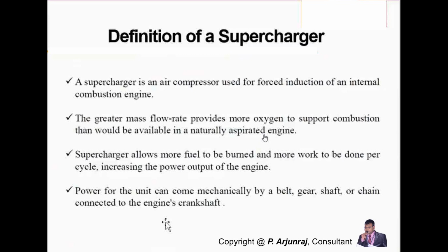And here this supercharger will help for increasing the mass flow rate of air, by providing more oxygen, and more oxygen will help for better combustion. That would not be available in the case of a naturally aspirated engine. What happens there? You don't have the external device called a turbocharger or supercharger, where the air enters at the normal atmospheric pressure, the same pressure it comes inside the system. But when you go for the supercharger, the flow rate gets increased.